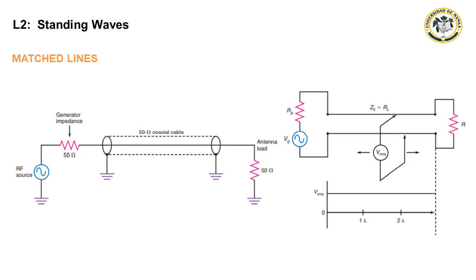When the load impedance and the characteristic impedance of the line match, the transmission goes smoothly and maximum power transfer takes place. The line can be any length. One of the key objectives in designing antenna transmission and transmission line systems is to ensure this match. A correctly terminated transmission line, therefore, is said to be flat. If the load impedance is different from the line characteristic impedance, not all the power transmitted is absorbed by the load. The power not absorbed by the load is reflected back toward the source.